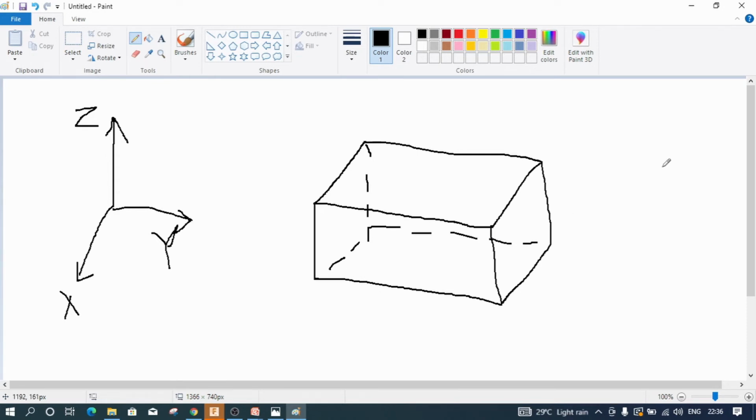So this is your cuboid, and if I want to create a hole inside this object, what will I do? That is known as removing the material. The command is the same, which is known as extrude or revolve, but you will be using that for removing. So what you will do is select this particular plane, and draw a circle.